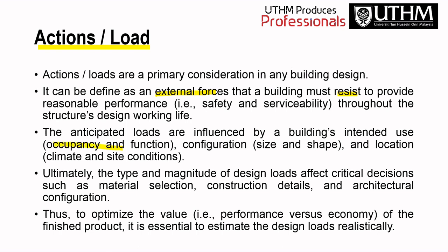Then the anticipated loads are influenced by a building's intended use, which is occupancy and functions, configuration, which is size and shapes, and also the location, which is about the climates and site conditions, such as if it's located at an earthquake zone, or in a four-season country with winter and snow loads. Ultimately, the type and magnitudes of the design load affect critical decisions such as material selections, construction details, and architectural configurations. Thus, to optimize the value, the performance versus economy of the finished product, it is essential to estimate the design load realistically.